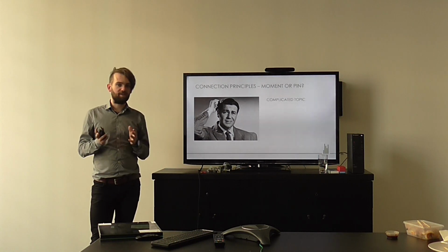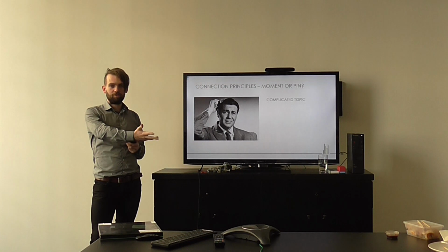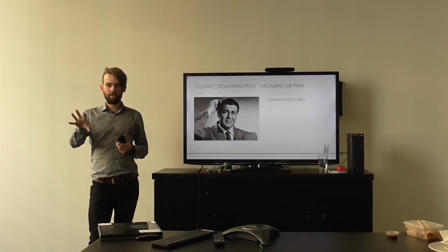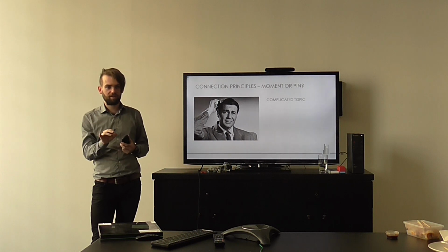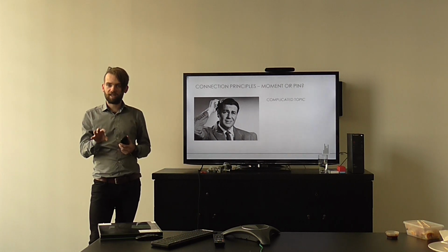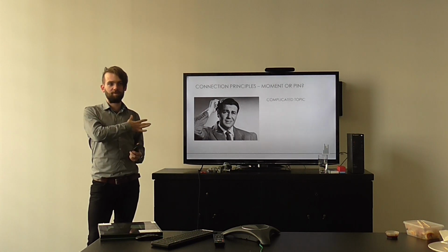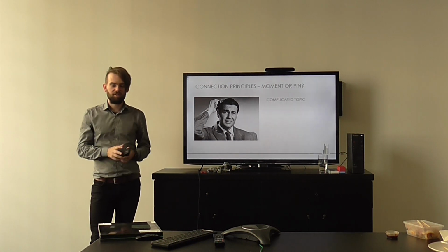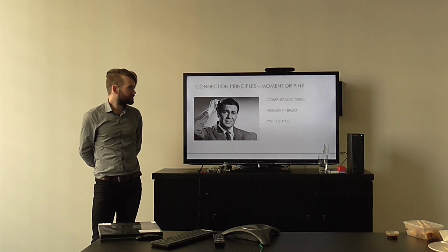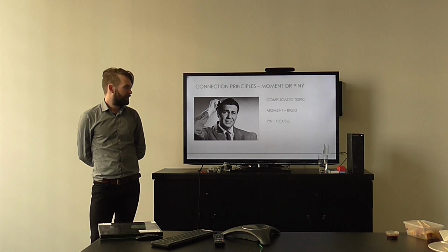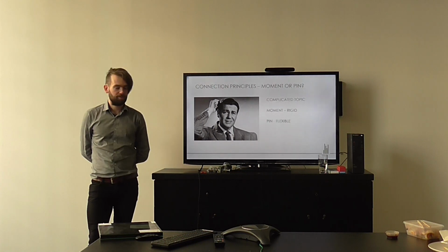And I guess the whole idea of this is that whether you're on the consulting side or in the drafting team, if a drawing comes across your desk, you might be able to identify from a couple of telltale signs what sort of connection that is. If you think there might be a problem with that, because of what we're about to speak about, you can go and speak to the engineering team. So, to break it down, a moment connection is what we call a rigid connection, and a pin connection is what's called a flexible connection.